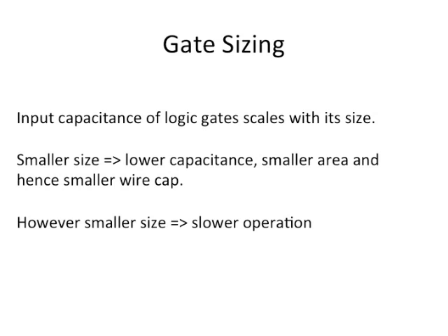So typically, when you have a digital circuit, you have a number of paths, right? In any pipe stage between the input flop and the output flop, you have a number of paths, and for a synchronous design, the speed of the circuit is determined by the worst case, the longest path, which is called the critical path.